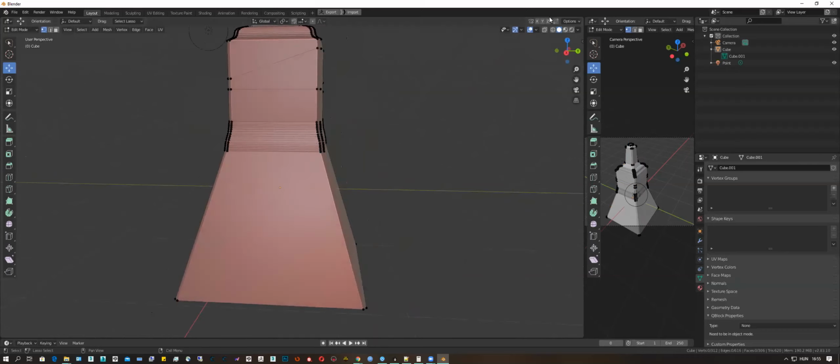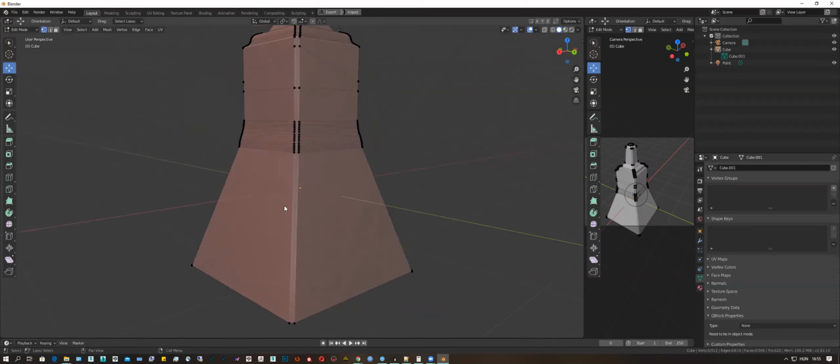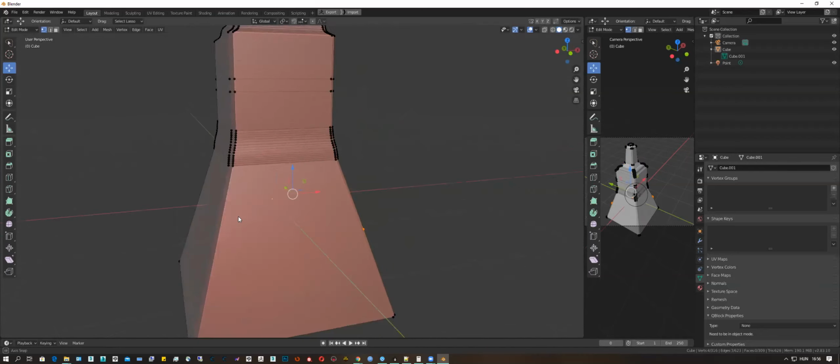However, if I would like to cut a straight line, I just press the key again and I cut it straight properly, snapping. I can press another button, C. As you see, it's helping me and it's making the cut from my view basically. So it's aligned to my view. And I can cut like this, press space, and there is a cut.